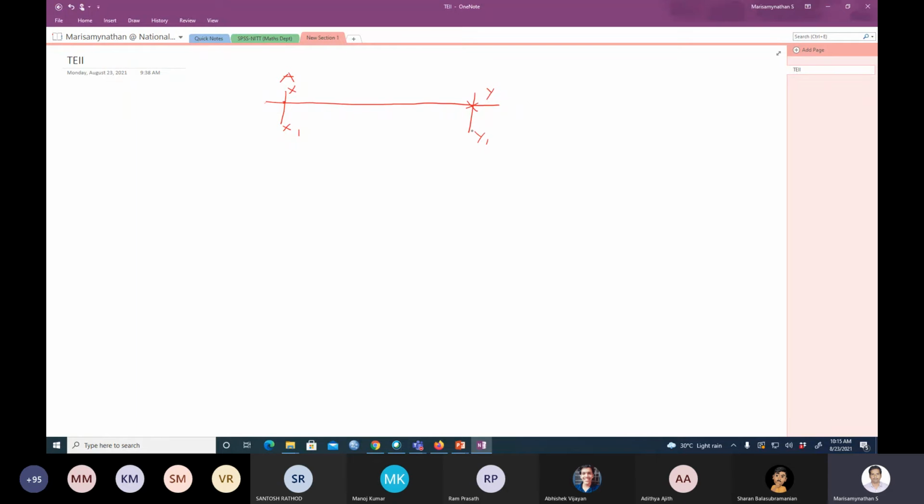As I mentioned, it's a simple definition. When the vehicle A touches this particular point, this point is considered as the starting point, where the eyes observe the obstacle which is existing at y1. Maybe a car or a pole exists. From this the driver is reacting, the PIV theory we have seen. Then he is taking the decision and trying to apply the brake, and he is stopping the vehicle to avoid the collision.